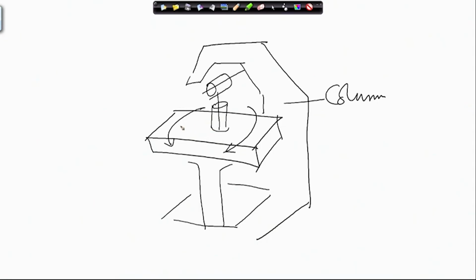In order to choose between directions, sense of motion for longitudinal or vertical or cross, we need a clutch. And in order to derive power from the main motor here, we need a telescopic shaft. A telescopic shaft is required. So, this one is like this, and somewhere here there will be that telescopic shaft by the side of the machine. Universal joints with telescopic shafts. Okay.